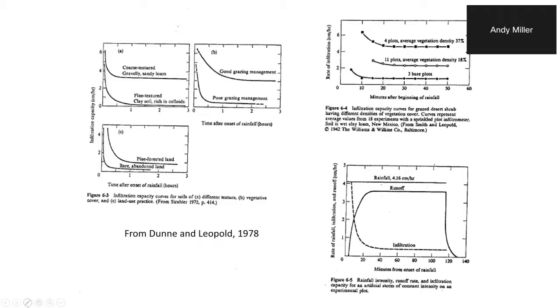When they compact the soil, you lose a lot of the porosity, and the pores become smaller. You lose a lot of the hydraulic conductivity or the infiltration capacity as well. So poorly managed agricultural land often has much higher runoff rates, just like poorly managed urban land or impervious cover, which has very low infiltration rates and very high runoff rates. Keep these things in mind, because when you model things you can actually simulate this kind of behavior over time on a given soil.